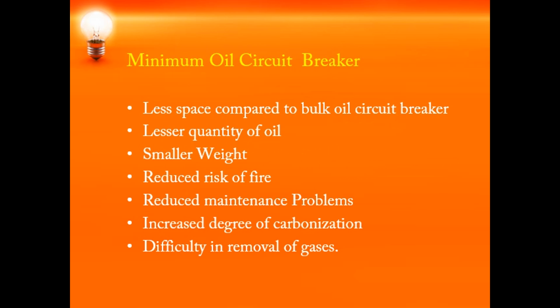we can go for a minimum oil circuit breaker, wherein a lesser quantity of oil is required compared to a bulk oil circuit breaker. This type of minimum oil circuit breaker is insulated from the earth, and you have a closed arc chamber also.